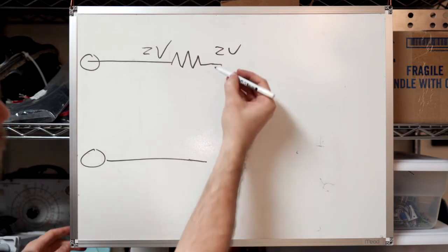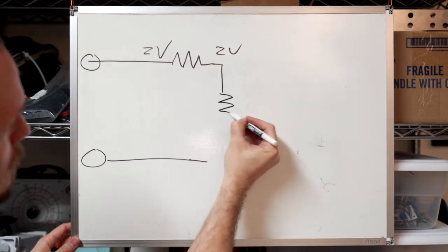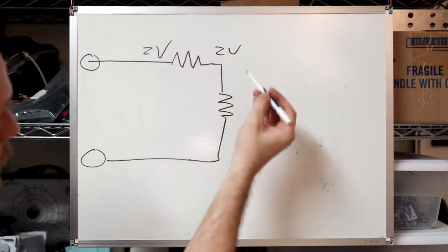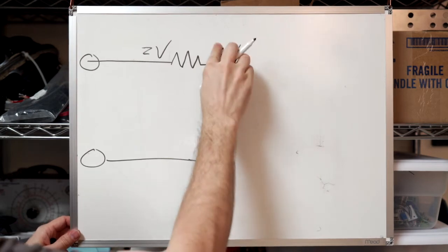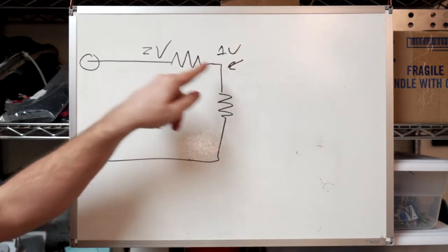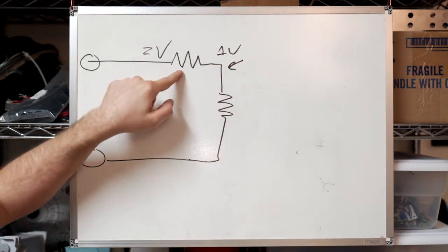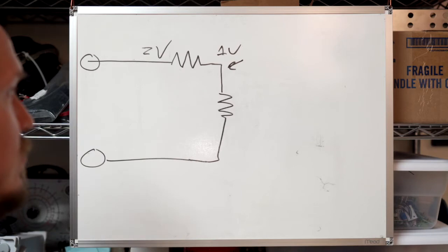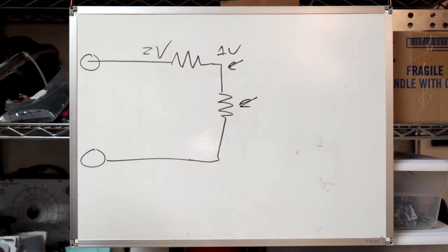So now what we can do is we can start putting values in here, like this, until we actually reduce this point right here to 1 volt, right? And once we've reached 1 volt there, we know that whatever this value is equal to the output impedance of the amplifier, right? And so we just measure this value then, and we know the output impedance of our amplifier.